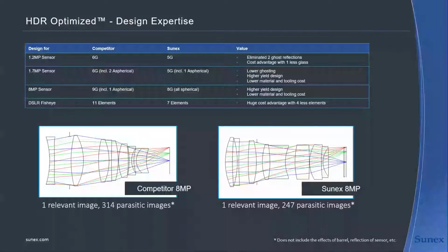So trying to design for fewer elements, again, always while achieving performance, is a criterion we're trying to achieve. And Ben, is there a break-even, right? We quite often say, oh, we need maybe an additional element to achieve a certain performance spec, like to correct for chromatic aberration or something. But at the same time, we don't want to have another element because you simply have two more surfaces where something can bounce off. So where's the trade-off?